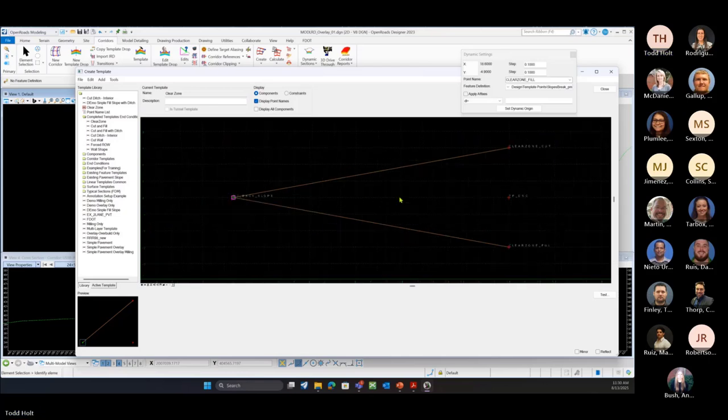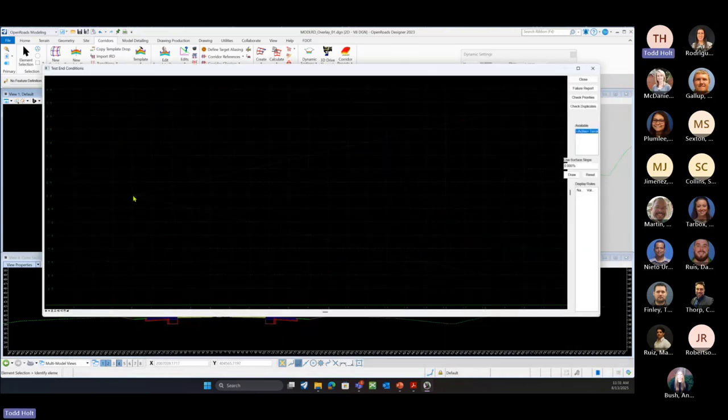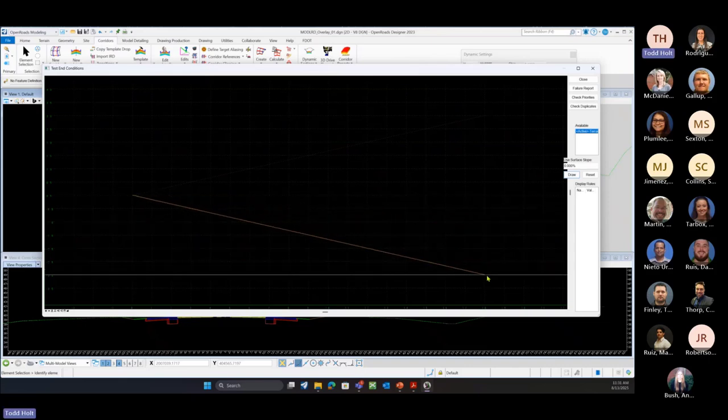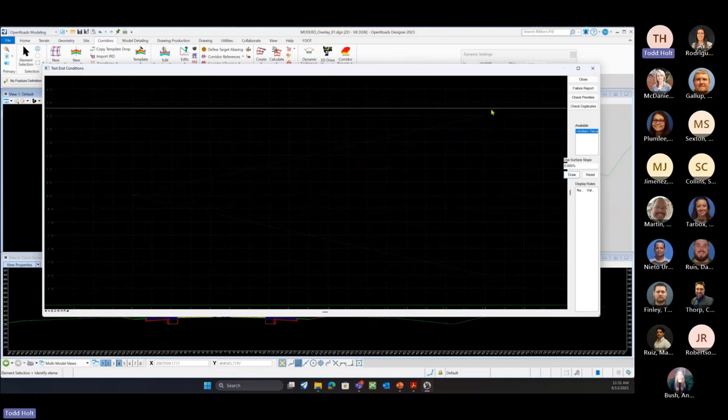feet. And then from this point to give our variable clear zone, cut, or fill, we're defining these to be 3 feet above this point and 3 feet below. So it's going to come and find the existing ground at 18 feet out. And then we can do a variable slope, whether it's above or below that existing ground. So now if we test this, there's our two slopes. If we draw our active terrain, that'll give us our criteria below it up to 3 feet or above and draw in there.